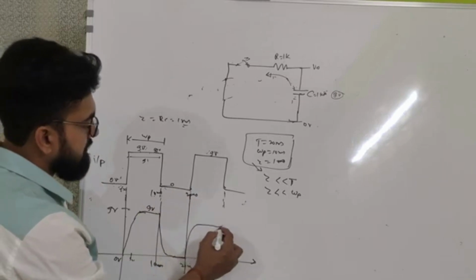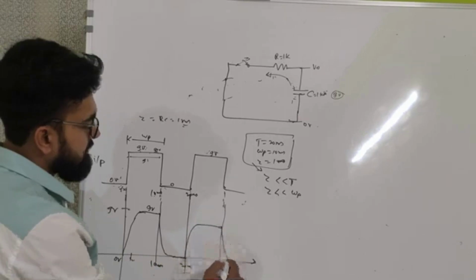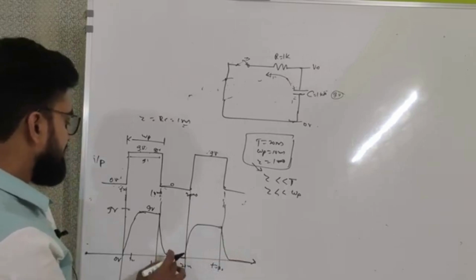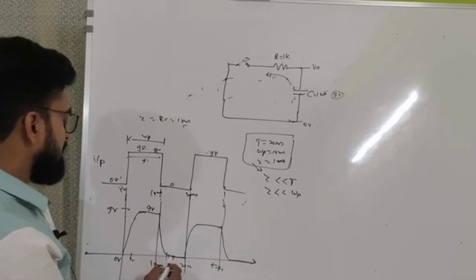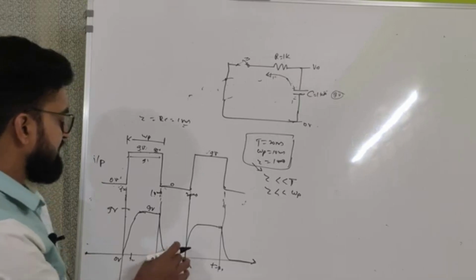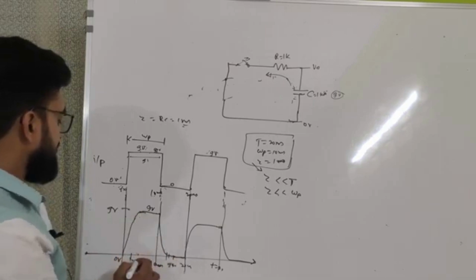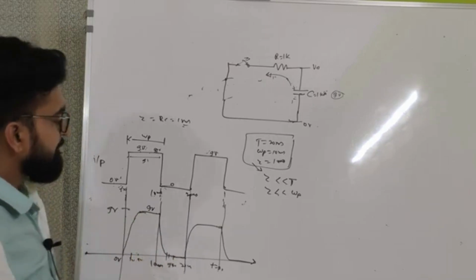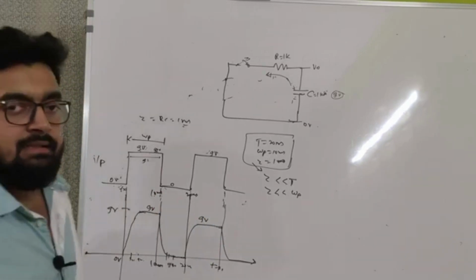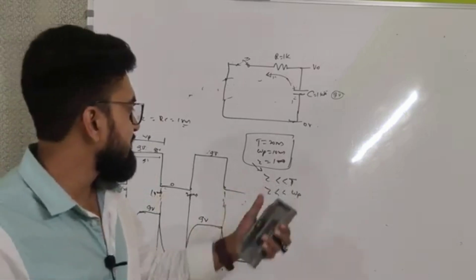It stays here at t equals 30. Discharges and again stays. So with this time constant, it will be almost completely settled down to 0 volt in 4 to 5 tau. Okay, so 4 to 5 milliseconds. Okay, so at 14 milliseconds it will be somewhere near here. Again here, exactly 9 volt would be somewhere near 4 tau, 4 to 5 milliseconds. Okay, so this is the rough sketch of an RC circuit where the time constant is much lesser than the time period of this circuit.